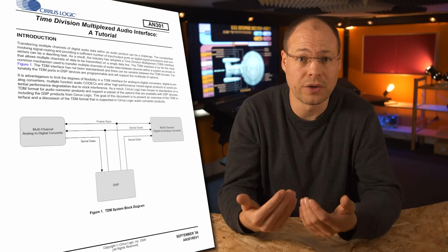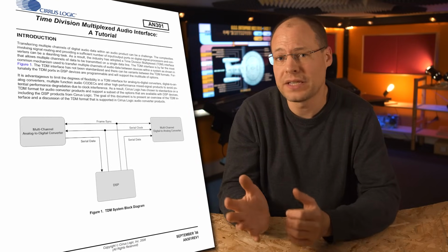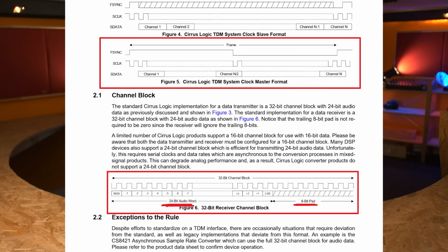As there are no frame sync and bit clock signals for the 4 return channels to the X32, these signals should take the main clocks of the console directly as a reference and transmit the bits back synchronously. As we now can use the basic concept of I2S protocol, the effort to receive 8 TDM-based audio channels is doable. Receiving is synchronized to the frame sync and the individual bits are read out with a bit clock. The rest of the system is based on the UltraNet mixer or FPGA audio player that I uploaded to GitHub.